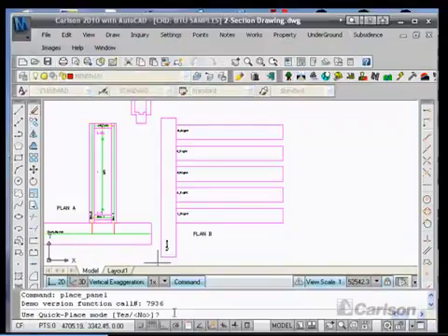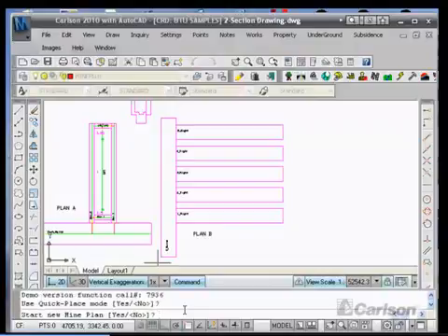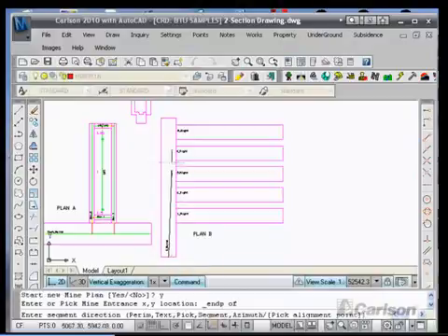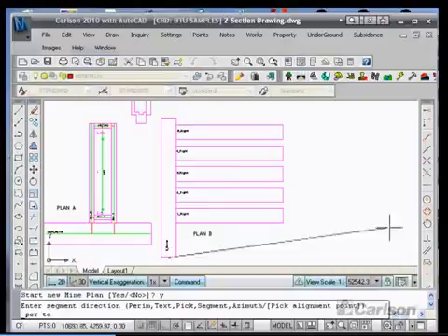At the command line, we'll get the option to use quick place mode, yes or no, and I usually decline this option. Starting mine plan, I'm going to say yes. Mine plan is just a list of panels. Enter or pick the mine entrance XY location. In this situation, I normally snap to, you could snap to the center of the panel here. If it's drawn with the advanced projections, then you use the endpoint option. Then I normally snap to the perpendicular of the back side of the panel.